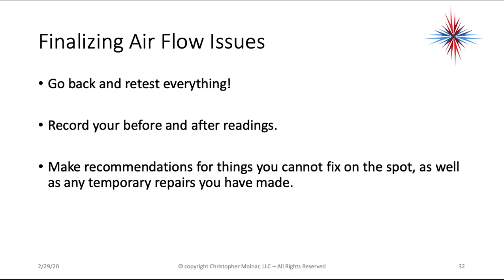Okay, if you've gone through and sealed a return duct with duct tape just to solve the problem immediately for the customer, sooner or later someone's going to have to go make a permanent fix on this. Okay, duct tape is not the answer to everything. Okay, if you find missing ductwork and you're able to seal it up a little bit, still somebody has to go through and make the change. If you find wet ductboard or wet insulation on sheet metal ductwork, you still have to make a recommendation for permanent repairs. You cannot leave wet ductwork forever. It's going to fall apart and it's going to cause mold.